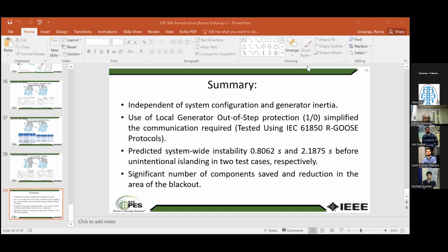Okay. If it is done offline, with some software like PSS/E, that is one software that is widely used, the Siemens PTI one, it sometimes takes a couple of days or weeks to run all those scenarios. That is where this RTDS real-time simulation became very handy. Yes, sir. When they were developed in the late 80s, 90s, they wanted to save time for the planning engineers. Real-time simulation means 10 seconds of simulation will take 10 seconds.